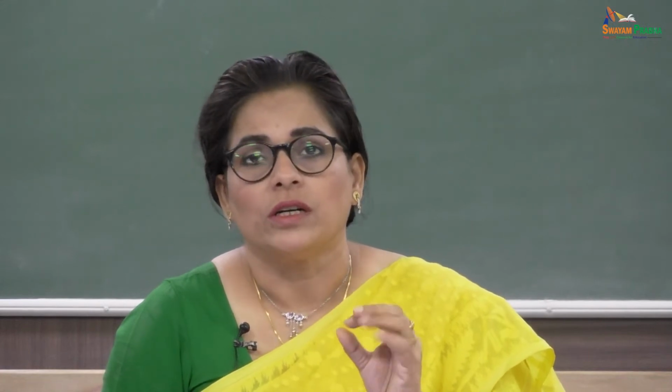So delta x has to be small enough. Domain size, let's say L, has to be large enough so that it will be able to contain the large eddies, and the grid size delta x should be small enough so that it will be able to account for the small scale motions happening in the dissipative range. I think that's what we're talking about.